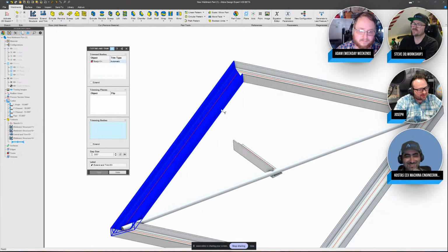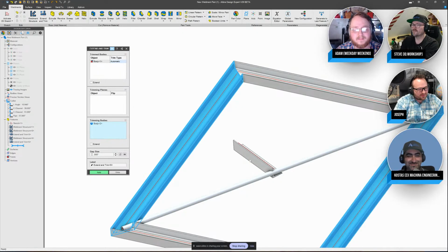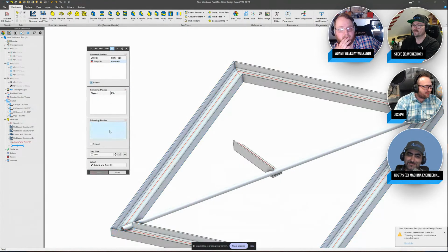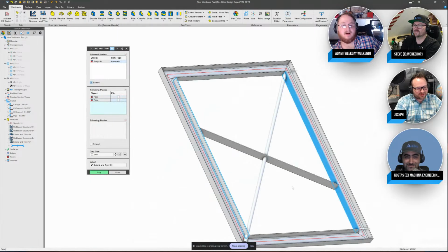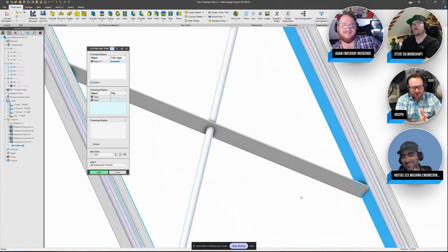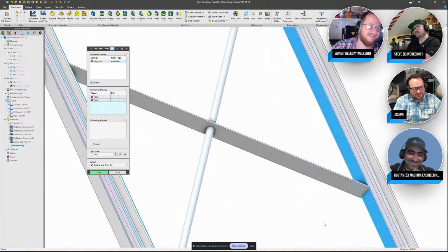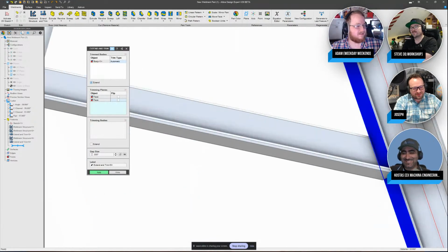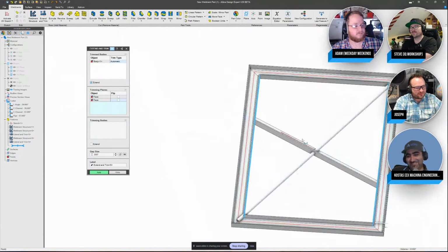One other thing I'd like to show is that I can trim this body on the things that aren't there, right? The way we do that is we just click extend up, and of course I need to choose the planes of these bodies, but we can extend straight to those things. So it's not just cutting apart, but you can extend it and end at the angle that you need to. There's a lot of flexibility built in.